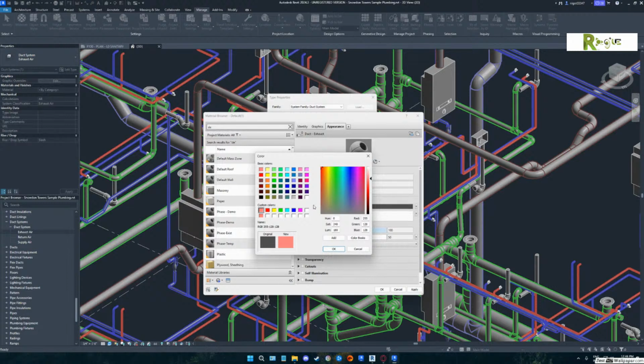So all I would do is probably drag up on the side view scroll bar on the right side. I would just lift that up just a little bit, not too much. You can go a little bit more than that. You want to be able to see a slight variation in the outline of the pipe and the face of the pipe. Correct. Like that much?